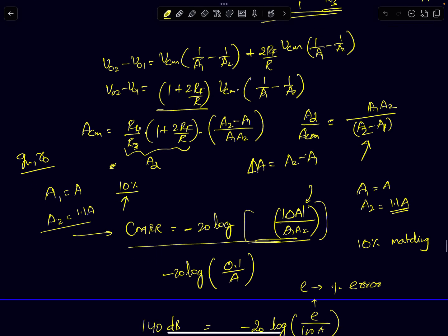These are all analog ICs. They are specially designed analog ICs, so you can expect them to have lower gain errors. But if you have CMOS ICs, let's say you are building this whole instrumentation amplifier architecture that goes into a CMOS chip, a chip that uses CMOS devices which are meant for digital design, meant for, let's say, DSP processors or microprocessors or microcontrollers.